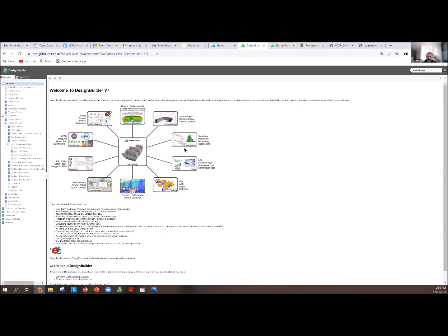Now, you really only need to use that when you have a building which has a large ground coupling. So suppose you've got a single floor building, or a building with 2 or 3 floors, then you need to worry about the coupling. If you've got a basement underneath your building, you don't need to worry about ground coupling because your basement is not conditioned, and above that is where the conditioning is. So your first conditioned floor is decoupled from the earth. Only when you have a slab on grade kind of building, which is a large ground floor, do you need to really worry about the ground coupling. So just be mindful of that. Every time you add layers on, the model takes longer to run, but certainly there is some increase in accuracy possible with that.